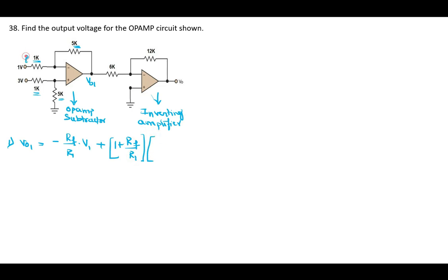What I am taking is, here this is R1, this is R2, this is R3, this is RF. Voltage divider rule, because the input applied here is through the resistor R3, I will write R3 by R2 plus R3 into the voltage applied. Okay, let us substitute.